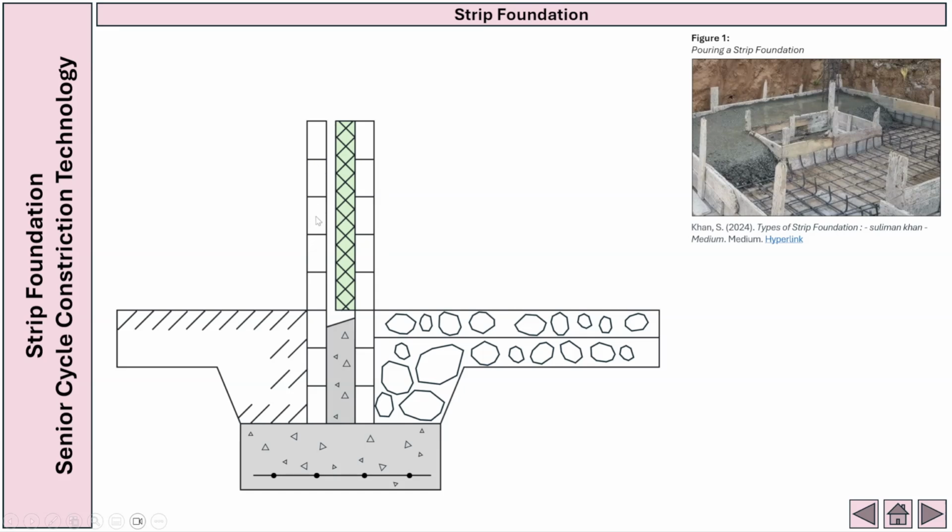So that will end up being 1000 millimeters or 100 millimeters from a scale of 1:10. And this is going to end up being 100 millimeters or 10, then 50 cavity, 100 insulation, and then a 50 internal leaf. So this is our external leaf here, our cavity, our insulation, and our internal leaf here. And all I've done here is I've gotten my 45-degree set square and I've just drawn a few lines up just like that, and then I just coloured it in green.